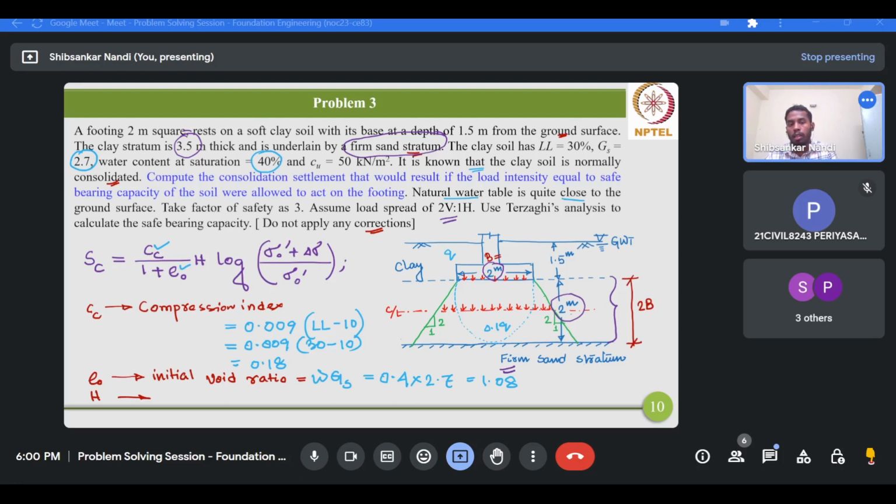Because as you know, this stress will get dispersed or distributed inside the soil mass. So the intensity which was at the foundation level will reduce as you go deeper inside the soil mass. So if you connect all the points where the vertical load intensity is 0.1 times Q, or any fraction of Q, by a line, you will get a bulb-like shape.